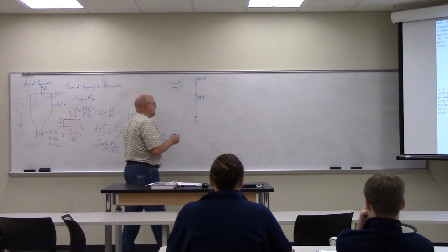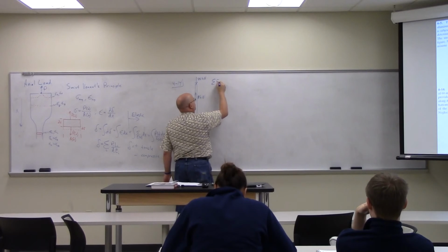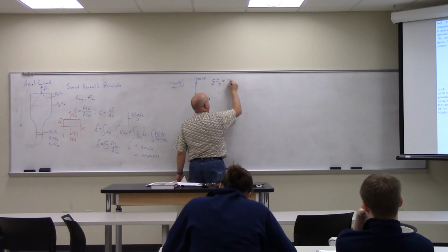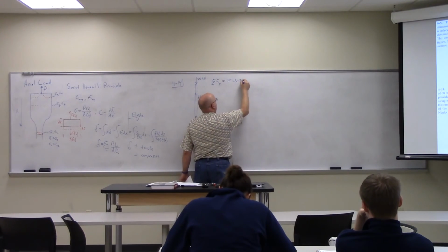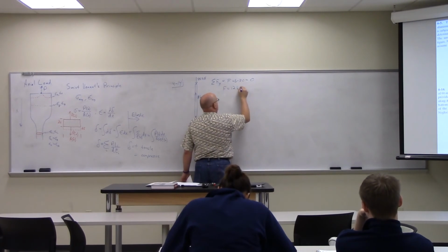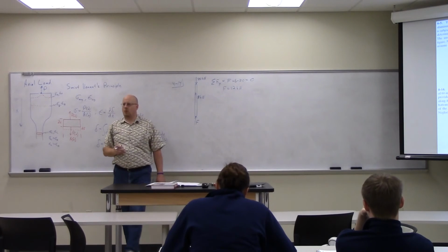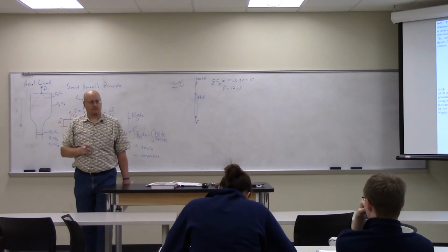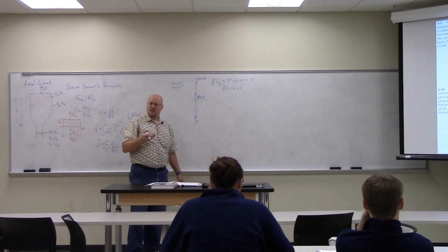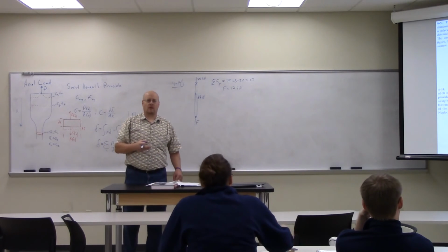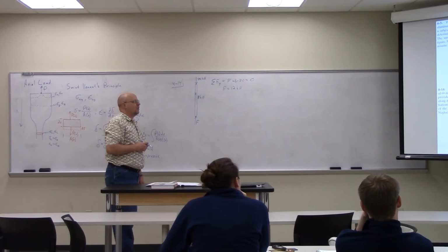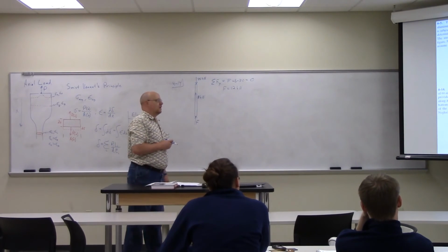Sum them. So, the sum of the forces in the y direction is F plus 8 minus 20 equals 0. F equals 12 kilonewtons. Now part A was just a piece of cake, easy peasy. But you figure it should be, because it's actually part B that's relevant to what we're doing in this section. So part B is: what is the displacement of the top of the post with respect to its bottom? Neglect the weight of the post.